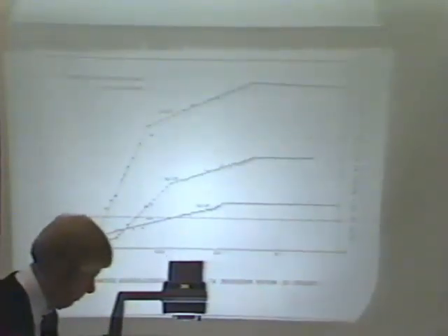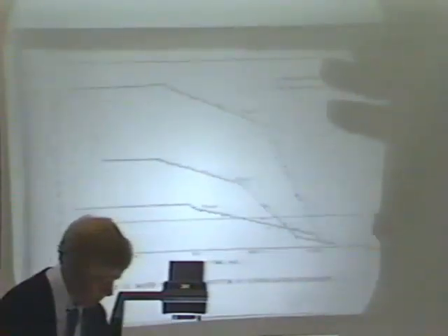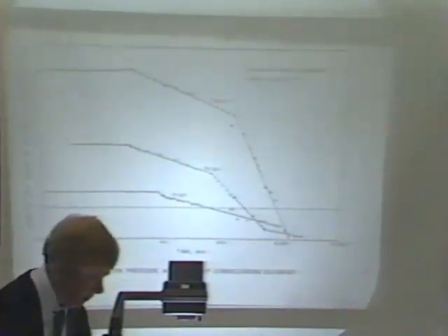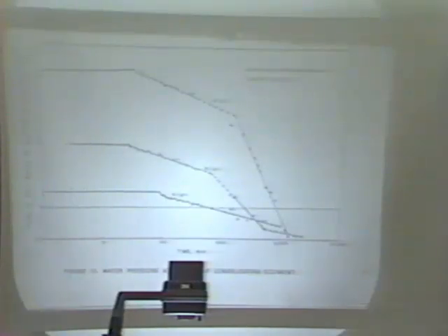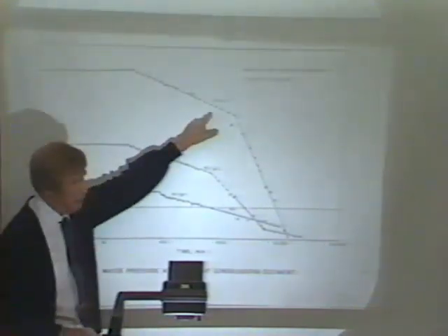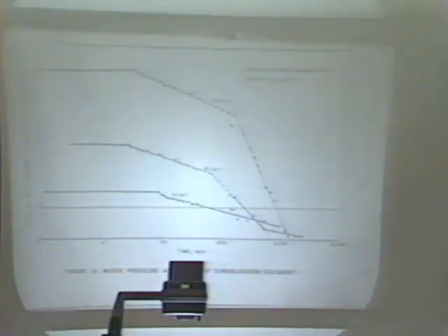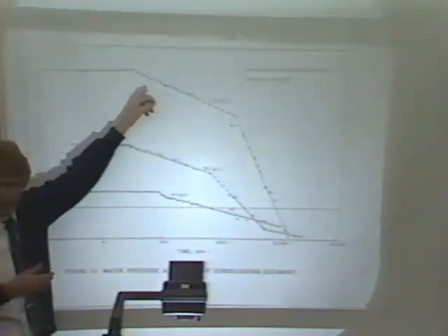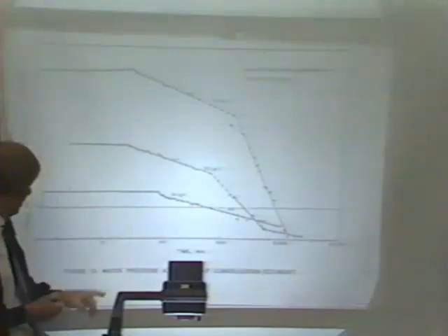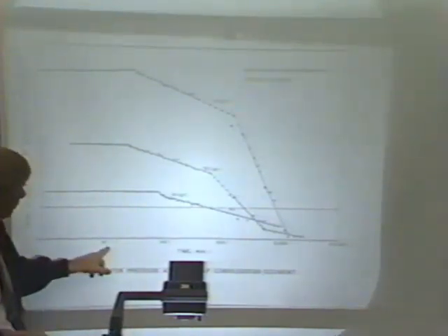now this is the pressure measured at the bottom of underneath that fritted plate by the manometer on the side. And one of them had 100 grams per liter of material. We suspended this with a plunger just as previously. And of course, for a while, the material was in suspension, and this is logarithmic time in minutes. So for about 15 minutes or so, 20 minutes, the material was in suspension. And of course, the density of the suspension was greater than that in the manometer tube. So the difference, this is centimeters, something over 2 centimeters